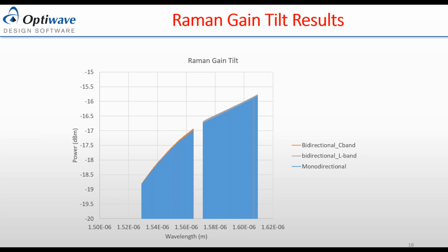This is the maximum peak gain you can get from Raman. You can use the OptiSystem software to tune the wavelength and get the maximum amplification with lower pump power, because this is an issue of cost. The more power, the more money you're going to pay for the laser. So it's a good tool for these kinds of designs.